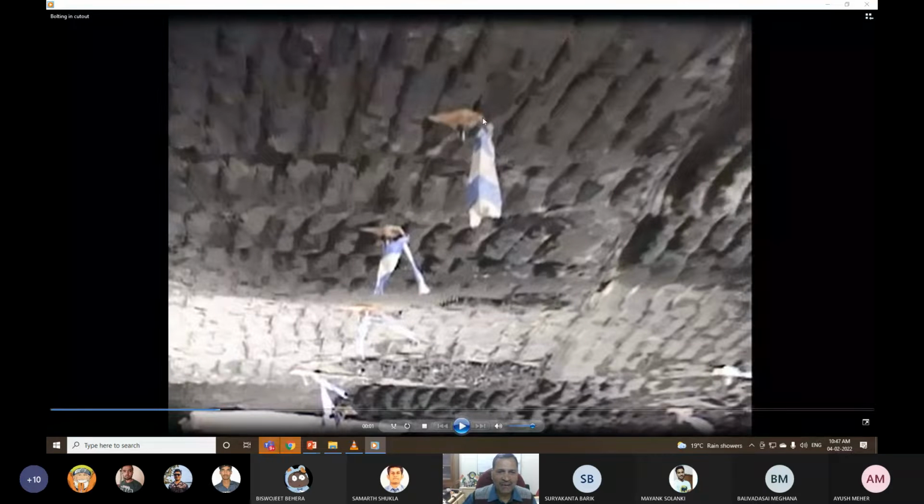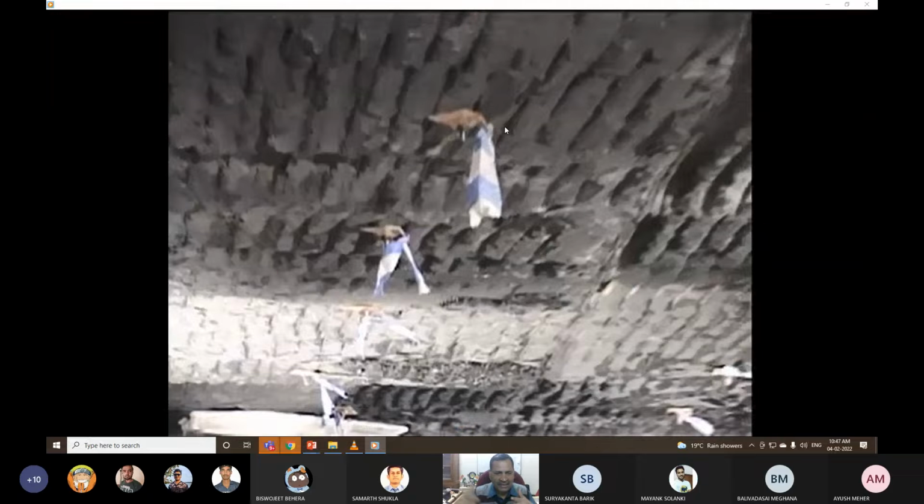So now you see how this bolting is done. When there is so much advance required, then we need fast bolting machines also. You cannot have a simple conventional way of one person going, or 3 persons in a timber mazdoor's crew, drilling holes manually with the 1.2 HP, 1.25 HP motor which we carry.